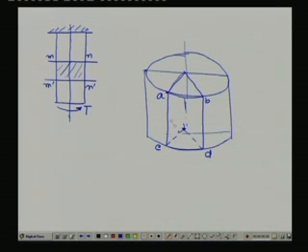Let us represent this element not in terms of T, but in terms of the shear stresses. So, obviously, the shear stress direction tau, referring back to the free body diagram. Here it is very important, you draw a free body diagram. If you make a cut onto this section, the torque will be in the opposite direction, in this direction.